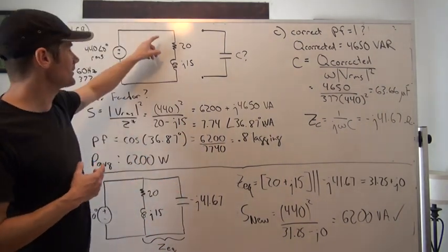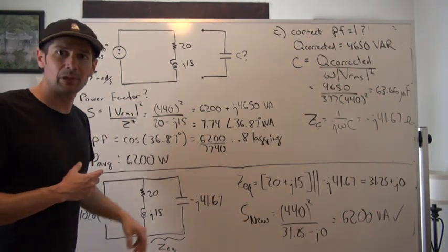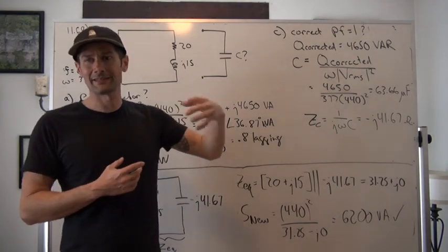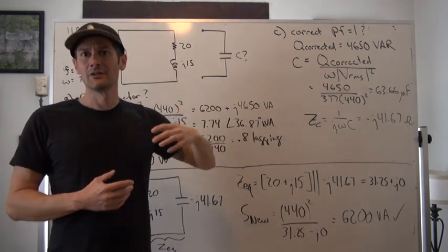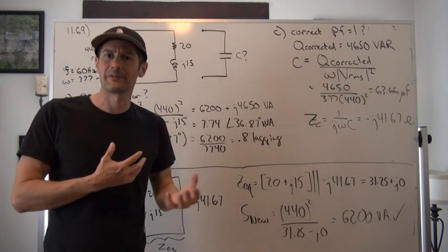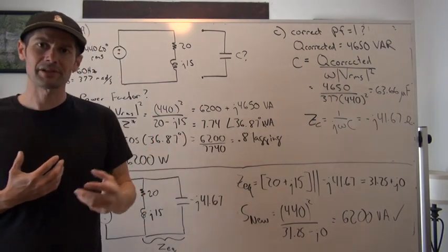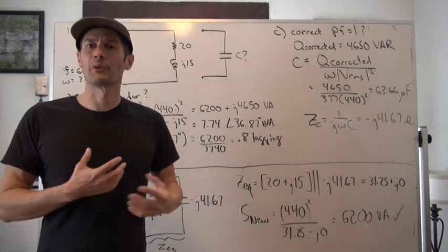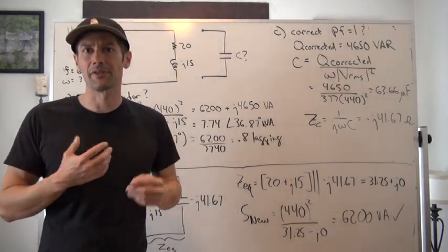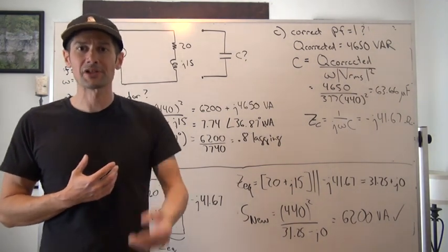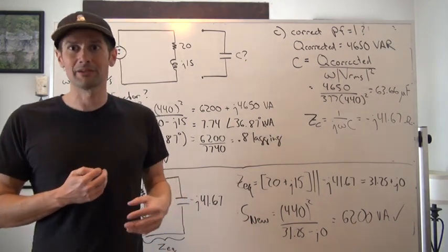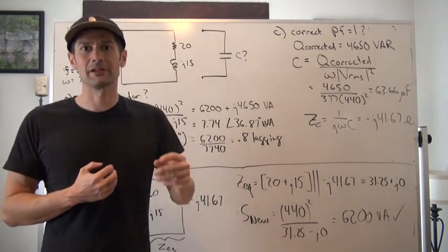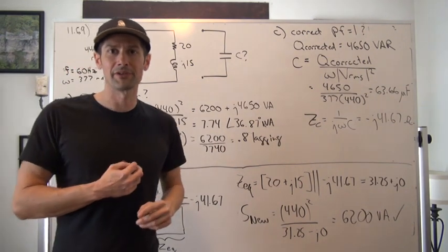So in this case, guys, what we're going to want to do is put a capacitor in parallel with that to correct that reactive power and have a negation effect, so that most of the real power within the system is absorbed within the resistor, and therefore we create efficiency and ensure that we are producing the smallest amplitude of instantaneous power to get the most real power within the system.